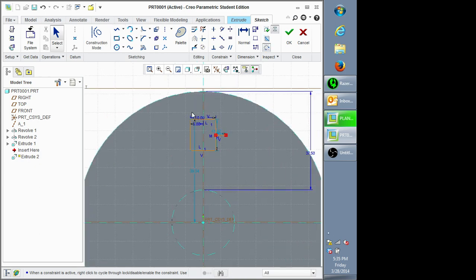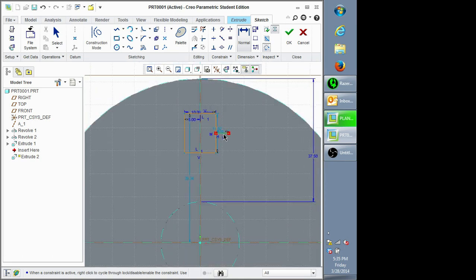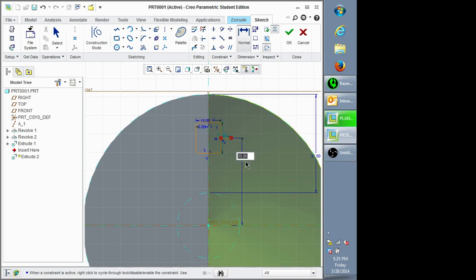So now let's dimension this entire shape from this line to here. So create a normal dimension. Make sure that this line highlights, and then select this reference point down here. And then middle click. And then a dimension pops up for it. So the whole, actually, never mind. Dang it. Sorry, I keep messing up. You want to select this circle, and then this line. Sorry.